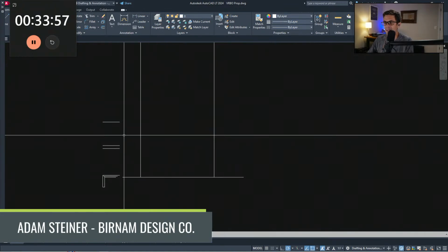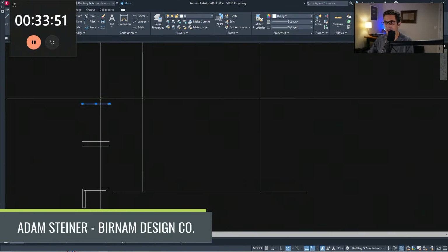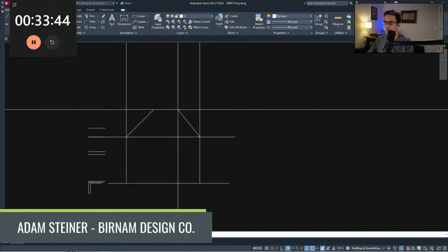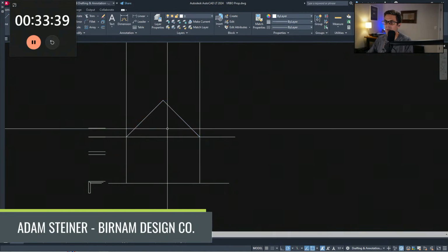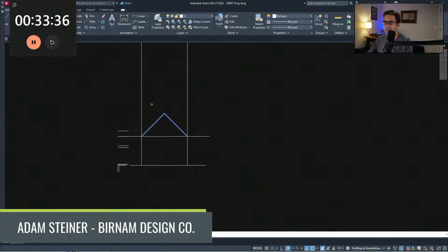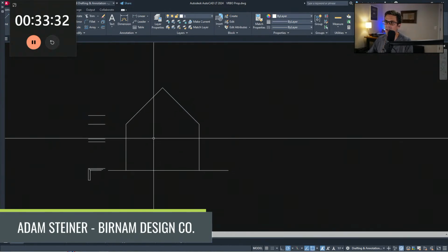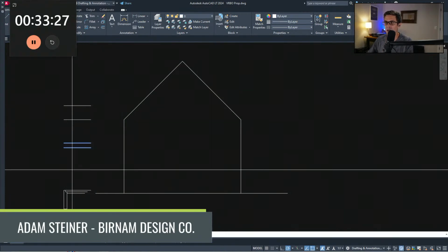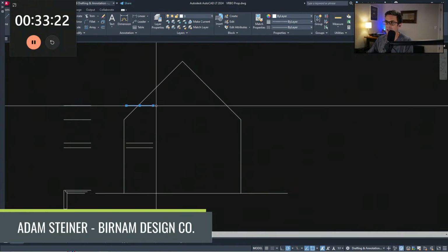But what I might show in something like this is a knee wall. So instead of an 8-foot plate, do like a 5-foot plate. And it matches the scale of the house a little bit better because it's going to be a smaller house. So they're 3 feet less tall, so not protruding as high. You won't have full head height in the corner of these rooms, right? If your floor joist is here, and then this is the line for an 8-foot ceiling.